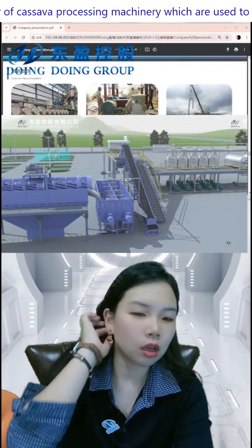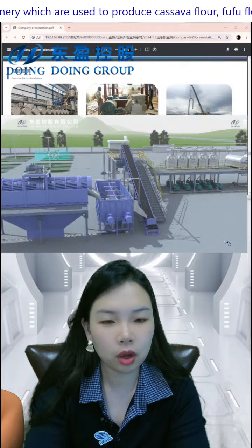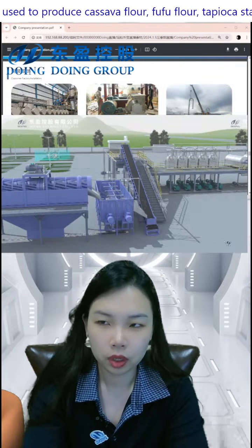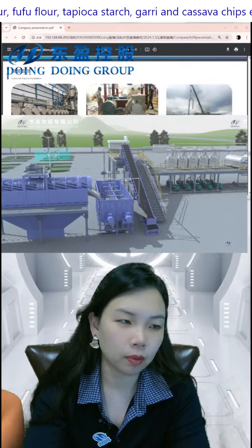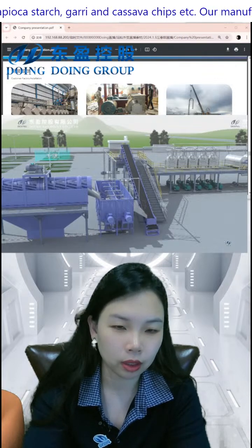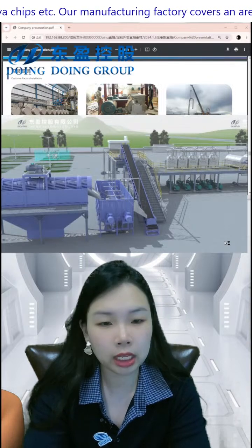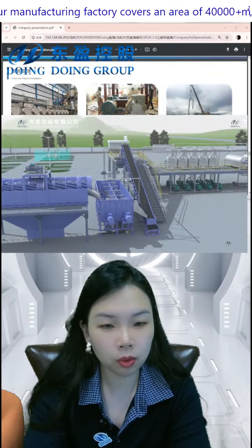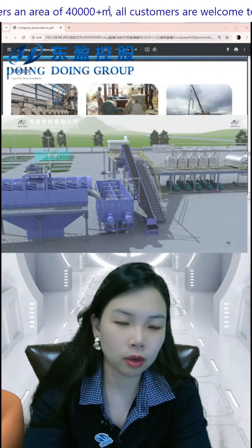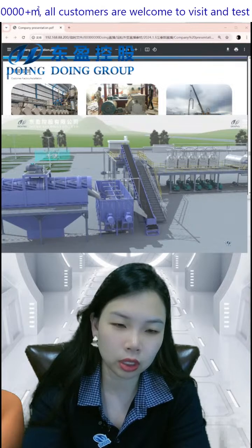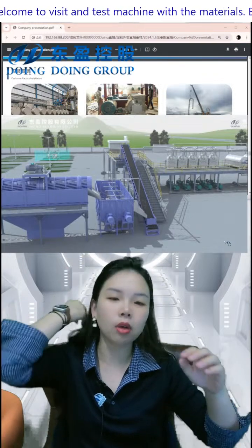Okay, and also during these 3 months, you will do other things, such as you have to get the water supplier to the factory, because for the fully automatic processing line, you have to get enough and suitable water supply, and also you have to test the water quality to confirm whether you need the water treatment system, not for the wastewater, but for the clean water.